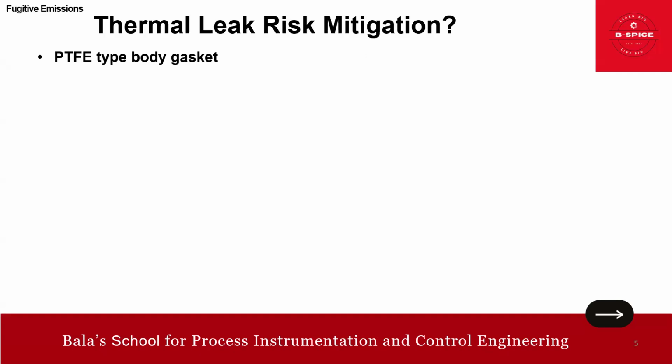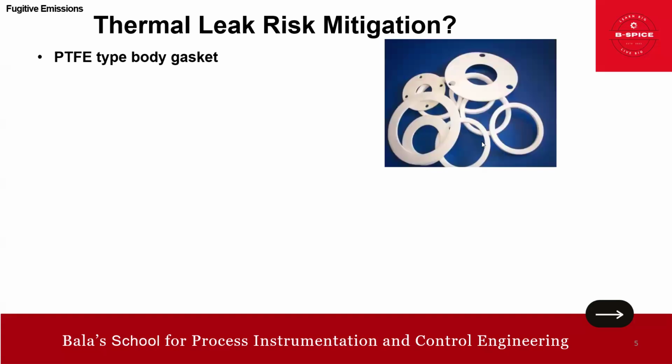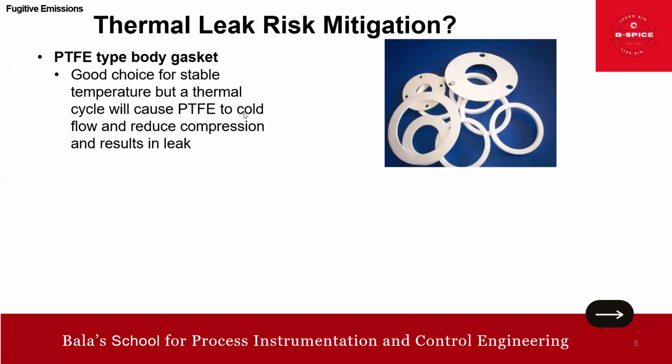Yes. So we need to consider a PTFE type body gasket, Teflon basically, right? This is the look and feel, right? So it's a good choice for stable temperature, but if it is subjected to thermal cycle, it will cause PTFE cold flow, and it reduces the compression, right? So it results in leak. That is one of the drawbacks actually.